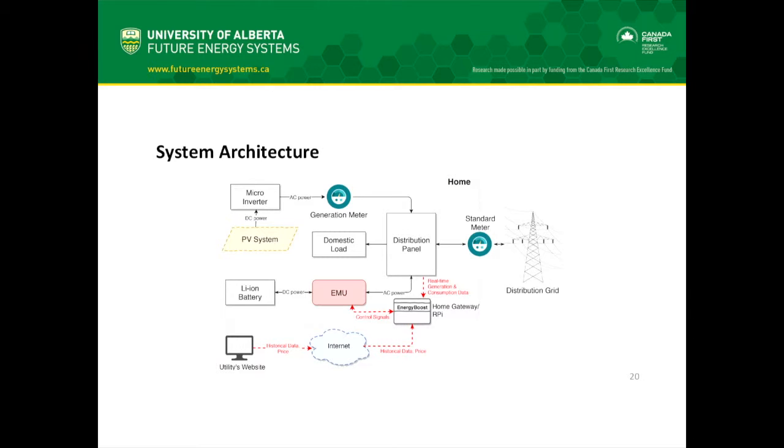We also have EMU, or Energy Management Unit, which actually plays the role of an actuator. This EMU charges or discharges the battery by transforming the AC and DC power together. And also we have some data from the internet that are being used for our system, which is here. This data is the pricing or historical data, and also the actual real-time values for PV generation that are being injected to here, and then this calculates if the battery should be charged or discharged.